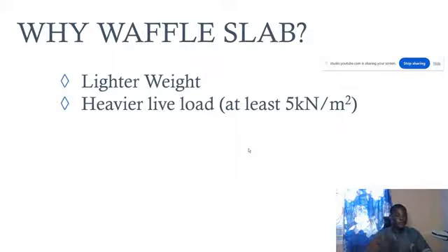That is when you can provide waffle slab and it will be economical. So it's very suitable for heavy live load. And because of that, we can say it can take a longer span. That is, the distance between supports can be as long as possible for a waffle slab as compared to other types of slab like ribbed, flat or solid slabs.